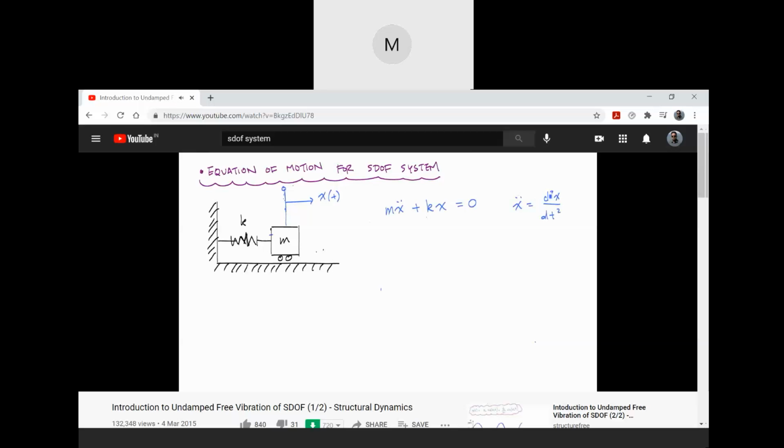And if you want to put something in free vibration, you have to give it an initial disturbance, right? You've got to introduce some initial conditions. So those can come in the form of displacement or velocity. You could say that for initial displacement at time t equals 0, I'm going to give this thing a pull. So I'm going to move x of 0 a distance, call it x naught.